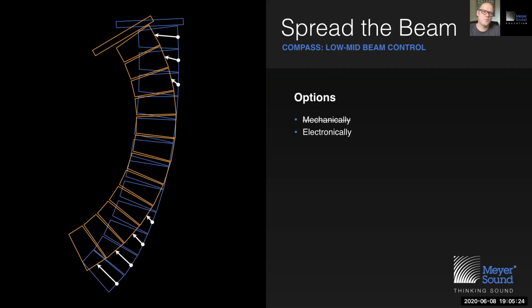So unlike subwoofers, which only operate in 1 or 2 octaves at most, we do not get to do this with line arrays. We cannot use pure delay in every individual loudspeaker, delaying all frequencies. The challenge becomes not to do this with electronic delay for all frequencies, but to do this by means of frequency dependent delay. And in Galaxy, the way to achieve frequency dependent delay is all pass filters.